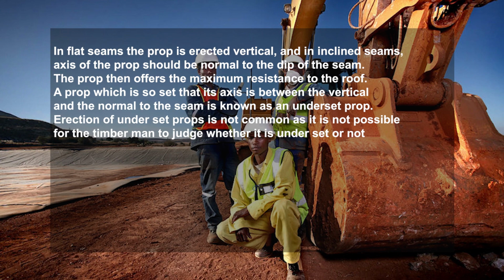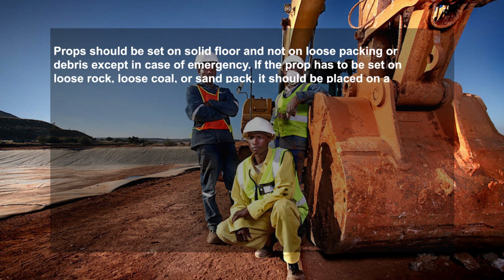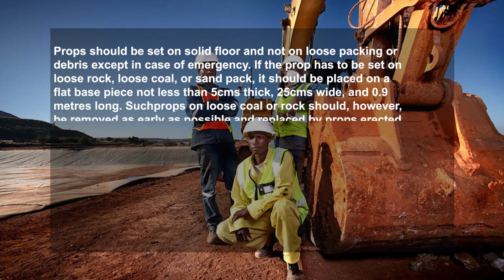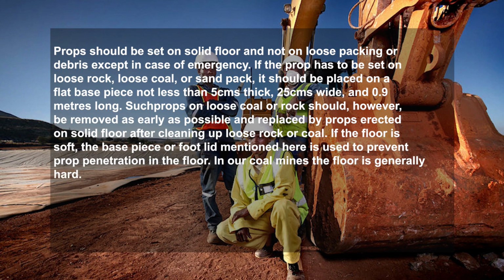A prop which is so set that its axis is between the vertical and the normal to the seam is known as an underset prop. Erection of underset props is not common, as it is not possible for the timberman to judge whether it is underset or not. Props should be set on solid floor and not on loose packing or debris, except in case of emergency.